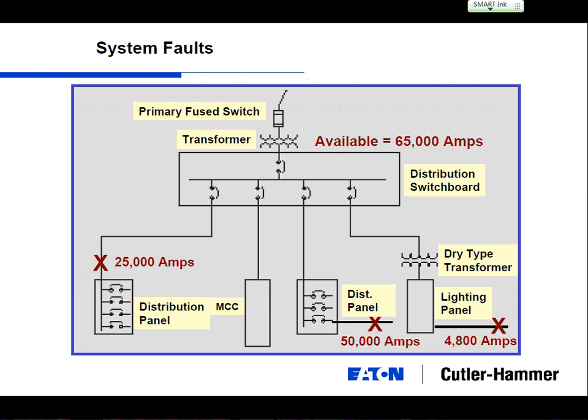For transformers, when you peel the skin off and look on the inside, there is voltage going through one coil that is going to induce voltage on the coil on the other side. So there's no true hardware connection between the two. Because you've got that air and that magnetized voltage you're creating on the second side, no matter what kind of fault you make, there's going to be enough resistance to set a fixed value of fault current coming out of that dry type transformer.